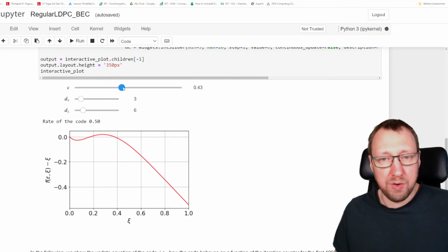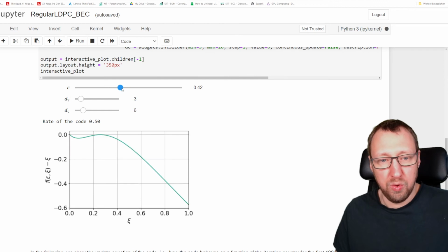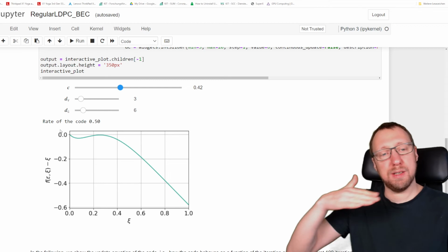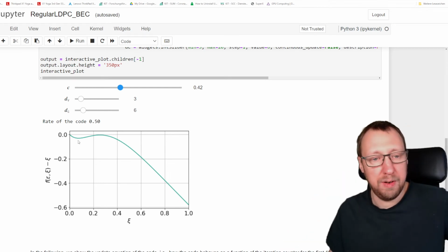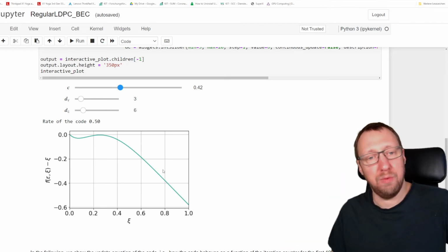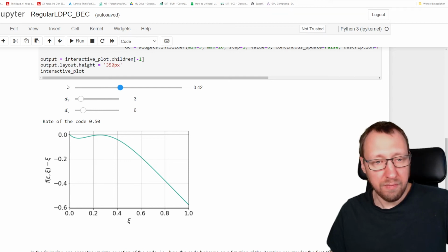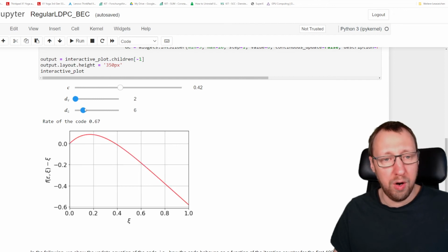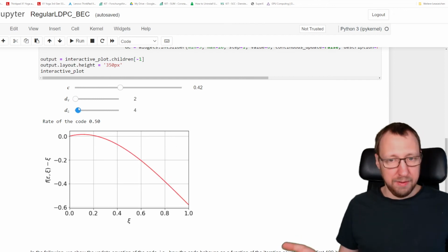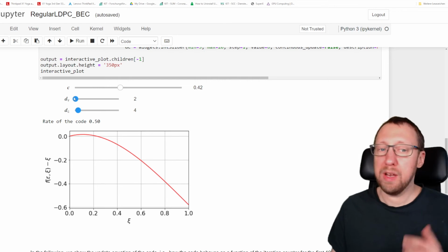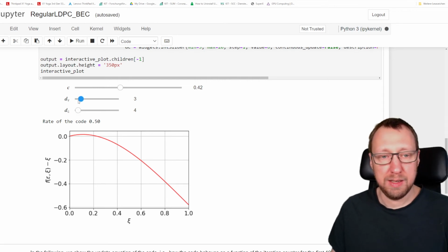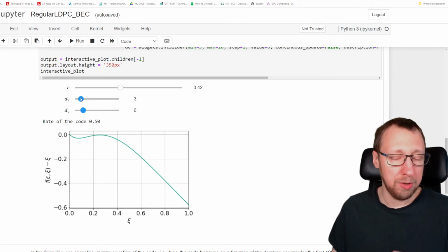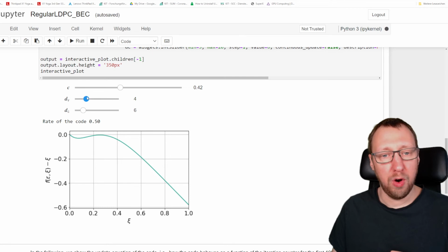But if we decrease to 0.4292, it gets green, which means we don't cross 0, there is no fixed point, and we can actually decode. So let's see what happens if we change the parameters of the code. 2.4 we saw already we cannot decode. So what happens if we increase dv and dc, so that we have the 3.6, rate 1 half code? We can decode. What happens if we go to 4.8?